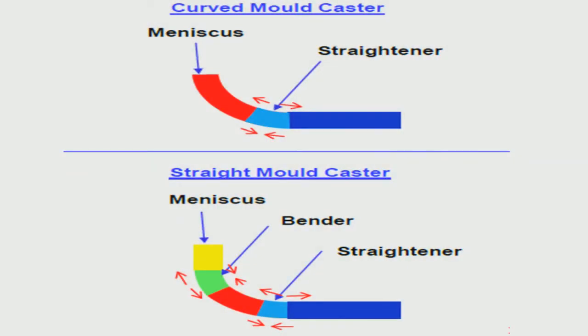Another important issue let me talk about during continuous casting, which can generate problems of entrapment at certain locations of continuous casting. I have mentioned earlier that continuous cast product is not having a uniform quality. Certain portions of the casting is relatively inferior in quality. I have mentioned at the start of casting and the end of casting, at the change of little changeover at the stage of sudden fluctuation, there is a possibility of entrapment. So, those areas are relatively inferior.